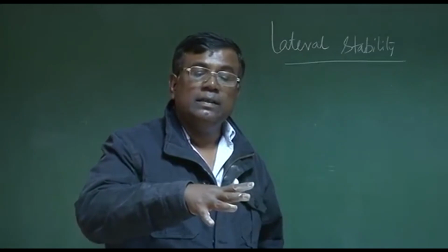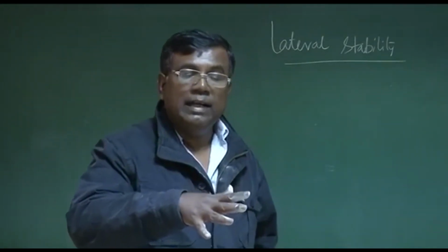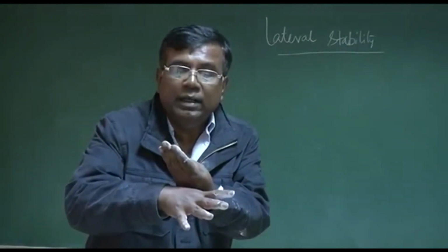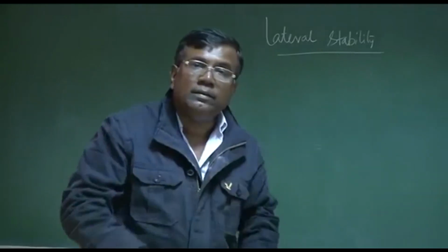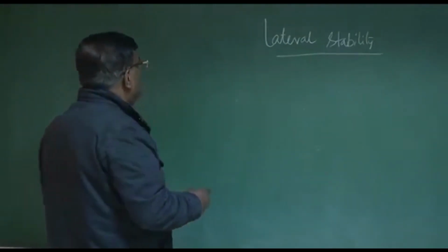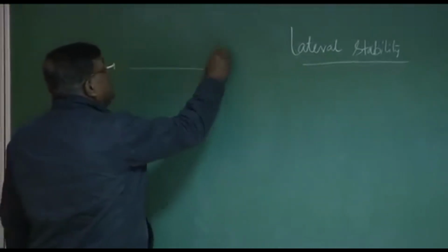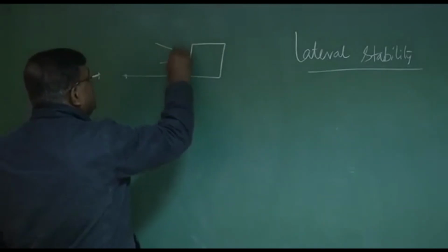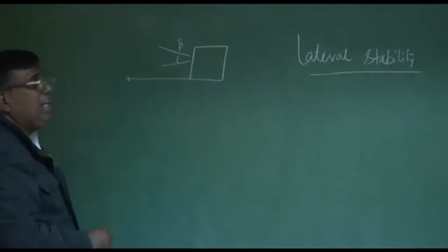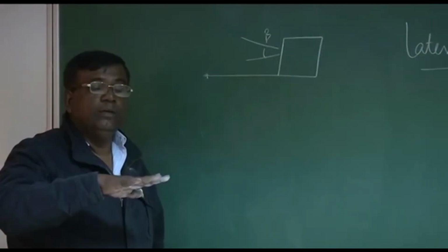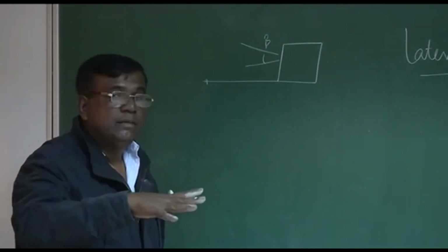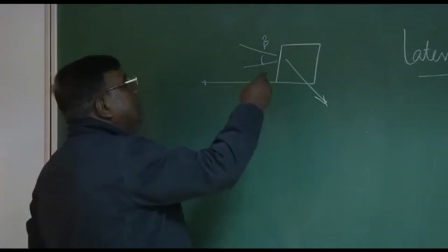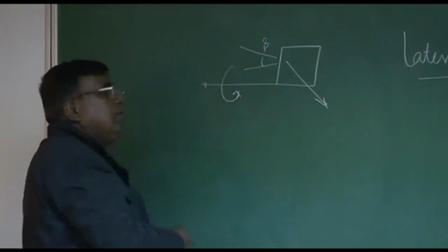As it rolls like this, the lift vector gets tilted, so it starts side slipping. As it side slips, since the vertical tail is here, that will generate a moment negative like this. This is clear? Suppose this is beta. Where from has this beta come? This beta has got induced because there is a roll disturbance like this and it starts side slipping. The moment the beta comes, this will give a force coming out of this plane, and that will try to give a rolling moment negative.